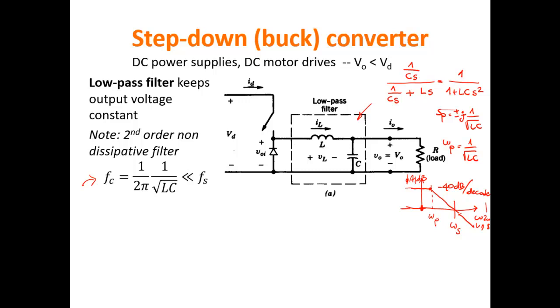And also in the case of a DC supply such as this one, if it becomes hot, then I need to find a way to dissipate the heat, because at something like 150 degrees, this stops working. So it cannot become too hot. And in order to make it not too hot, I need to dissipate the heat faster. Typically, in order to dissipate the heat, I need to make it larger, because if it's larger, it has a larger surface, and it's easier to dissipate the heat.